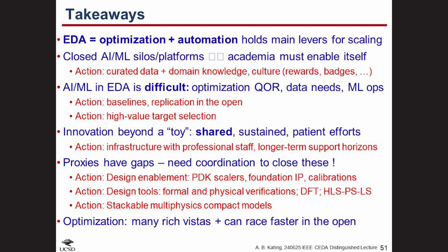Number 2 example for optimization, this classic high-value target of enabling faster and more accurate exploration of architecture and SoC floor plan options. Shortening the time to useful PPA feedback is incredibly valuable. So this macro placer, hierarchical RTLMP, which is MPL2 in OpenROAD, understands RTL hierarchy and data flow. Some great professional engineers helped Jiang Wang and Ravi develop it. It delivers very human expert-like results.